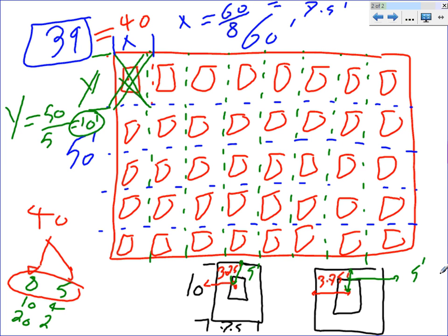This calculation, guys, does not have to be 2x4. It could be round cans. It could be any type of fixture. So what if you don't have a grid? Then that will get you the start of how to lay out your fixtures to get the best lighting distribution system.